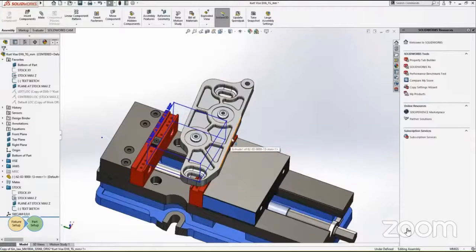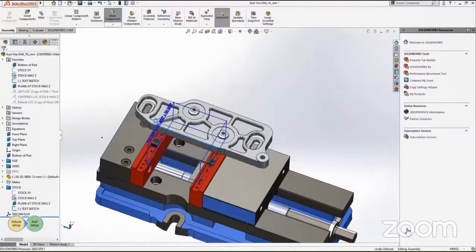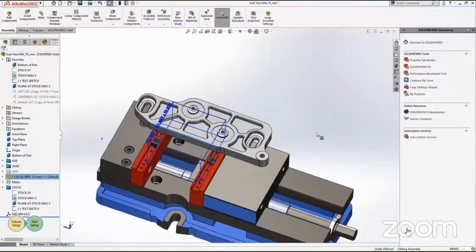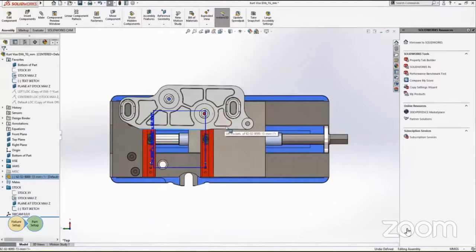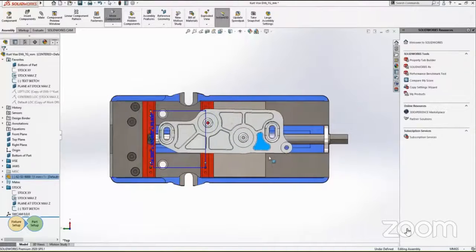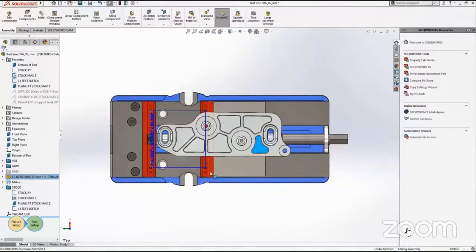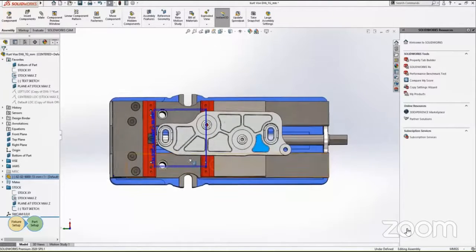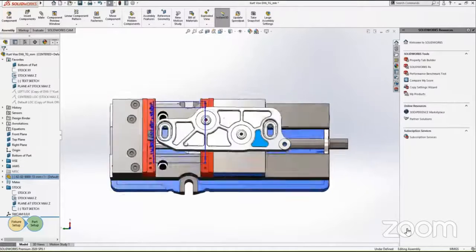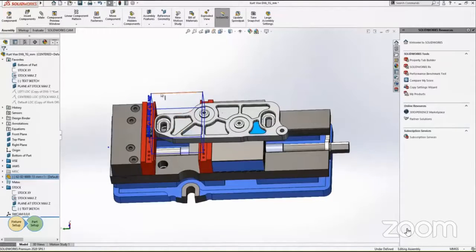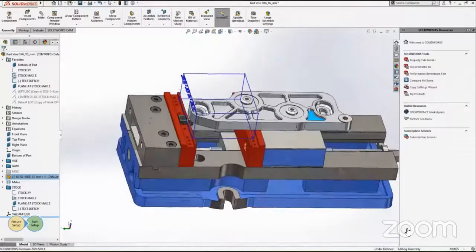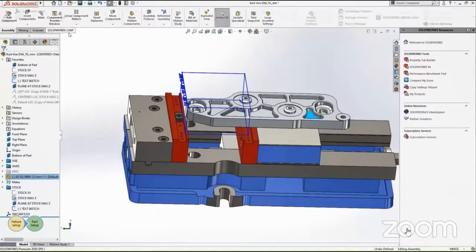All right. So let's say if I want to change the orientation, I press the right click of the mouse and rotate this part. If I go for the top view, I can press the right click and move my mouse in the upward direction. It will show me the top view of the CAD file. So with a simple click, I can drag and adjust the file in a position I want. So in SolidWorks CAM, we have an additional add-on which is used for resizing the stock sketch. So this is a sketch and it's not completely enclosing the whole CAD file.